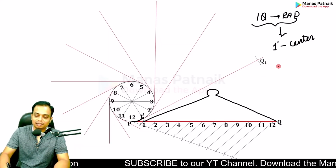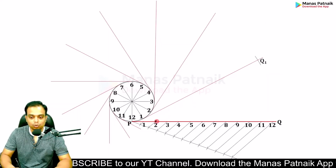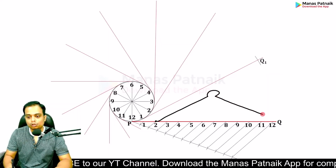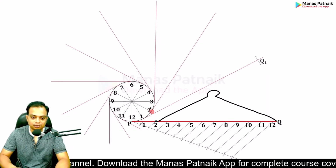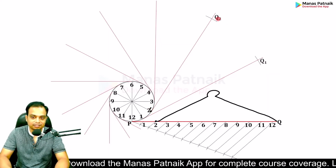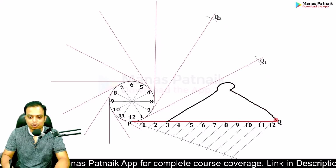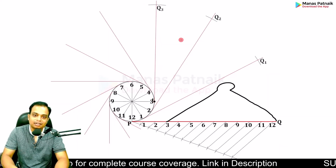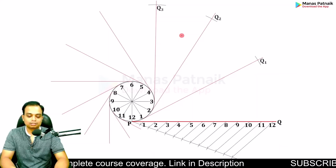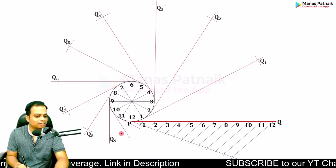Similarly, now with 2Q as the radius and with 2 dash as the center, cut an arc again. This is Q2. Done sir. Similarly with 3Q as the radius and with 3 dash as the center, cut an arc. This is going to give rise to Q3. Similarly, you can obtain points Q4, Q5, Q6, Q7, Q8, Q9, Q10.